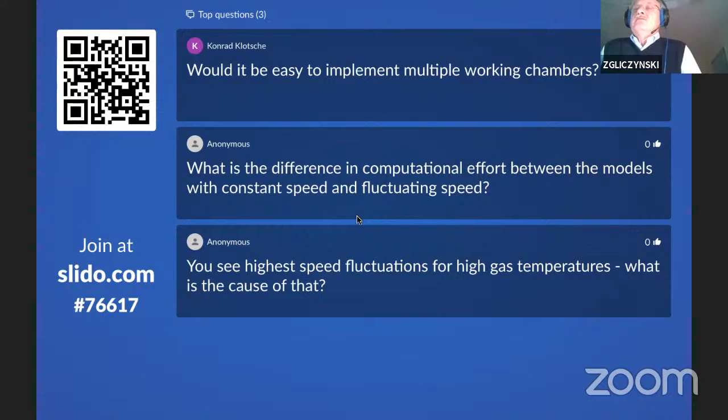Can I make a question? Okay. Thank you for your answer. Thank you. Yes. Tiago, question here from my side. Obviously, the inertia of the system is the basic reason for those fluctuations. So you have the variable load, and you have basically torque that is changing. So the coupling of those two things creates the fluctuation of the speed, which obviously creates issues in the bearings because of the speed variation.